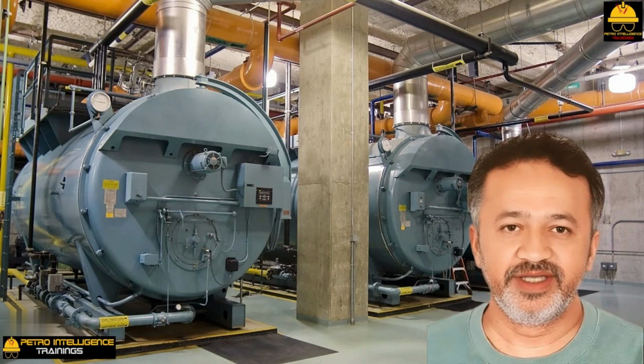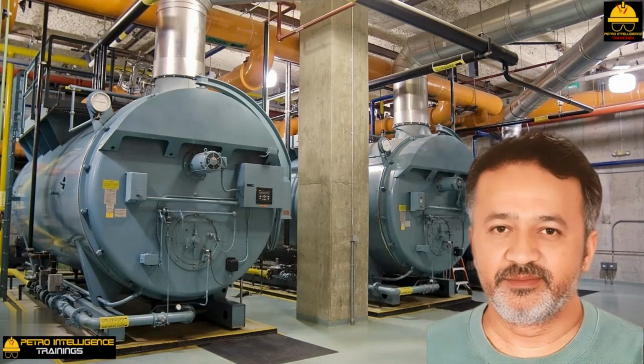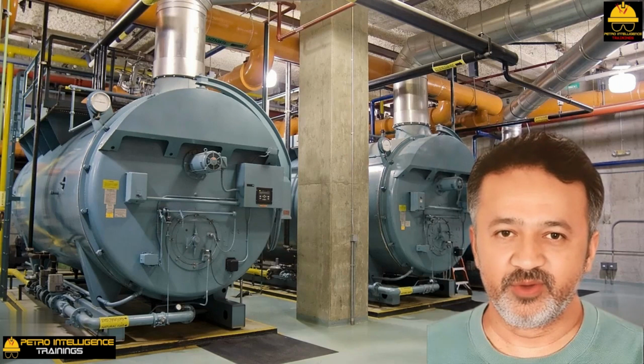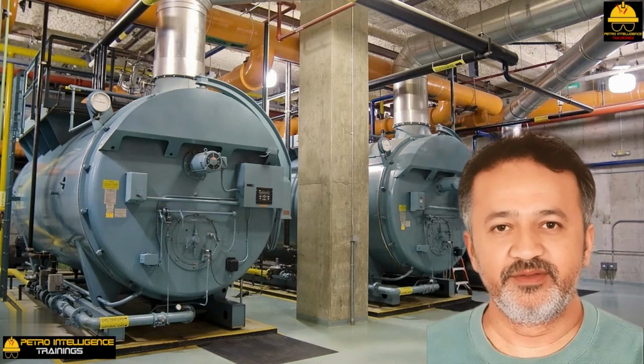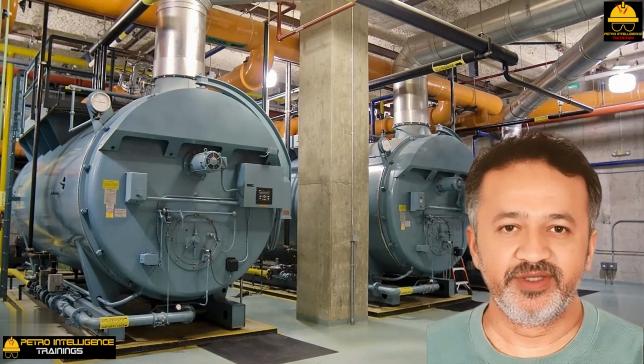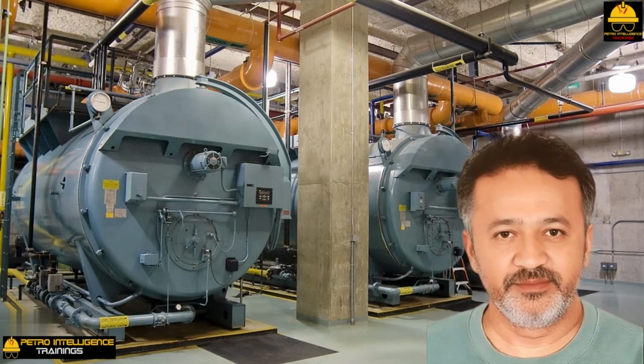If low sulfur fuel, less than 100 ppm H2S, is being fired, H2SO4 corrosion should not be a problem. For boilers firing fuel oil, bunker, it's best to preheat the BFW externally to perhaps 350 degrees Fahrenheit to protect the boiler's economizer convective tubes from corrosion. If a small amount of vaporization occurs in the preheat exchanger, this should not compromise the operation of the economizer, provided that there is only a single inlet to the economizer section.